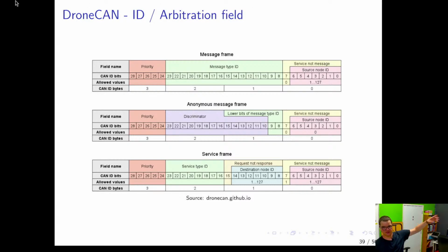There's a kind of handshake, and you're assigned one, but you need a service. So in a drone environment, the autopilot is running a little server that assigns node IDs, but you'd have to run it. The DroneCAN GUI tool also has it.